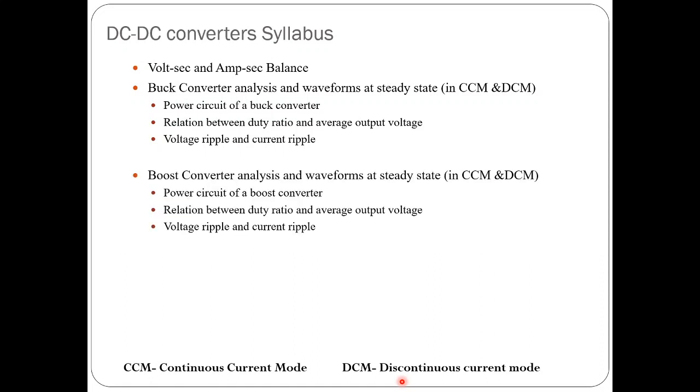Next we shall see boost converter analysis including the required waveforms in both cases. That is case 1, continuous current mode, and case 2, discontinuous current mode. In both cases we shall see the power circuit and then the relation between output voltage, input voltage and duty ratio, voltage ripple and current ripple.